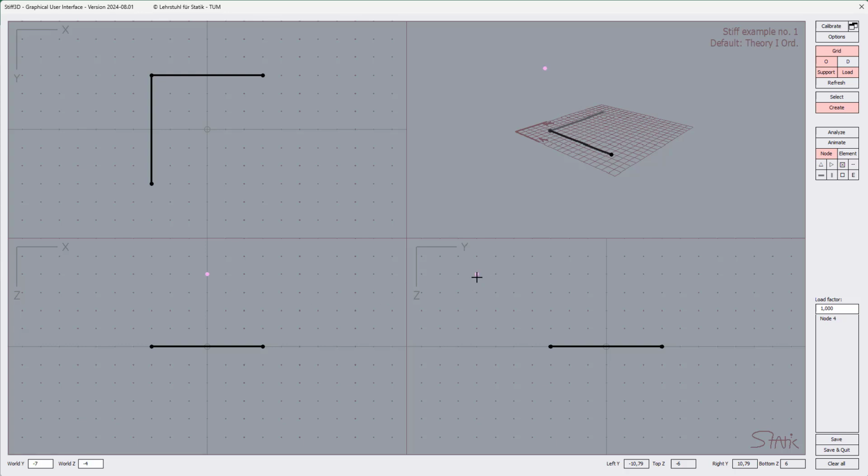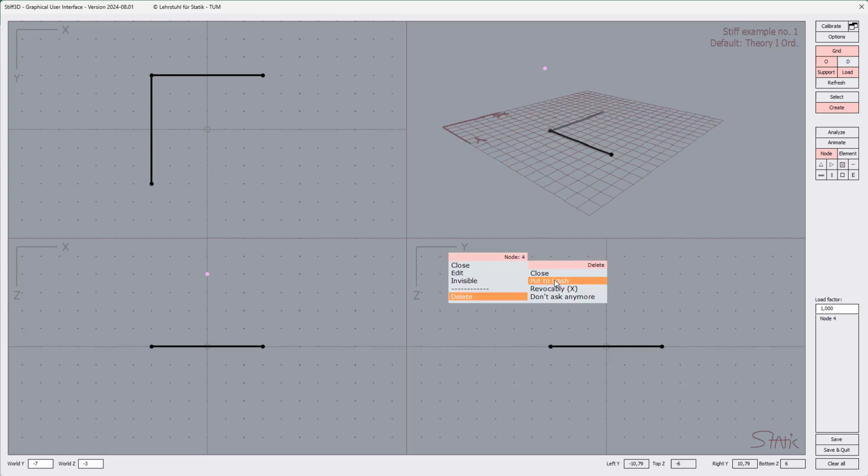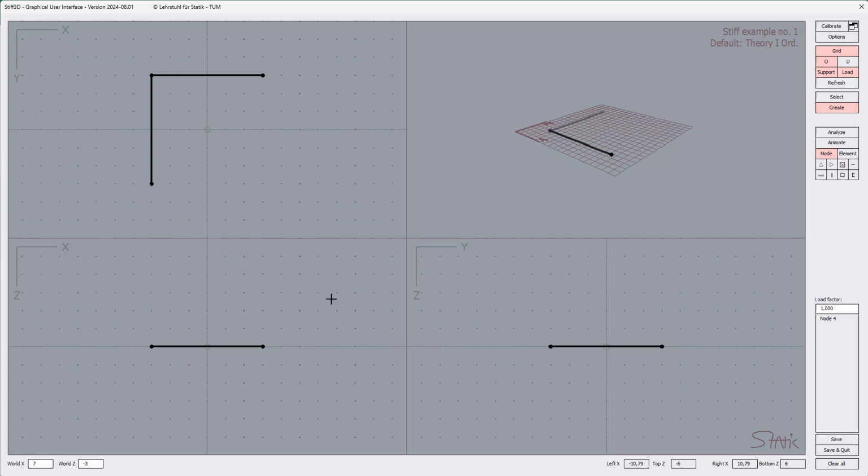I create a node here, and you see this node with the respective y and z coordinates, just by selection with the cursor, receives automatically the value of this crosshair. And that's exactly how we can create nodes on a respective level. And that means creating a node here on a level somewhere below. We simply shift the crosshair to there. I create a node, and you see this node with the coordinates x equal to 5, y equal to 2 receives automatically the z coordinate 4.